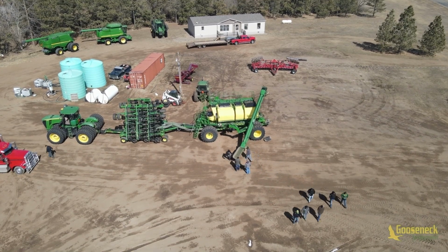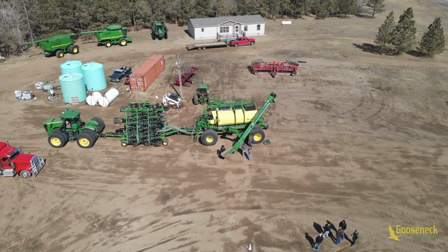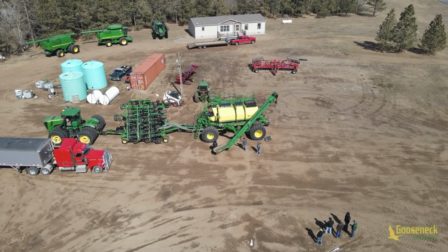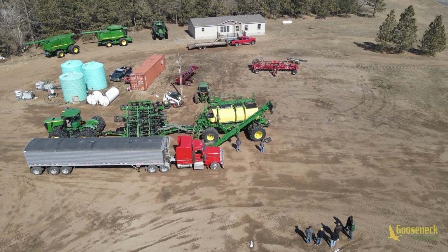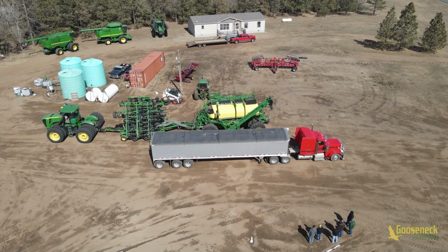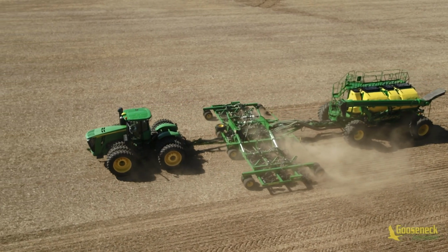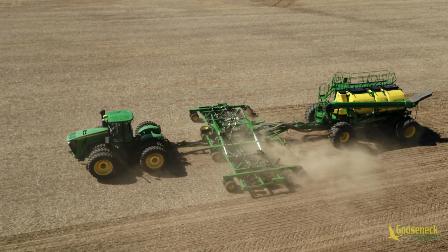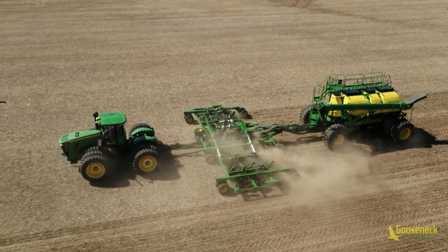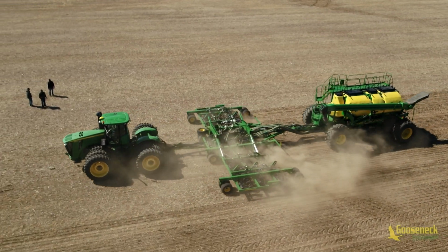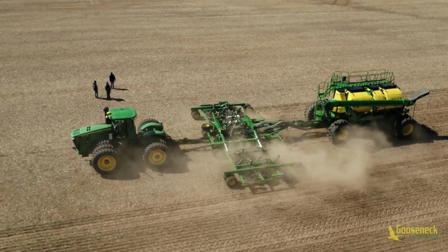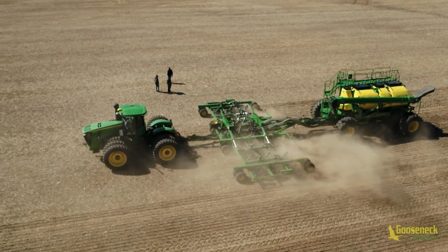The next step is to verify our times. We'll verify the times with an in-field test. First, we need to simulate a headland. We will need a minimum of 3 passes so we have enough room to do a complete turnaround while entering and exiting the headland. While making the 3 passes, we will need the disc in the ground to have a cut mark or some point to measure from.